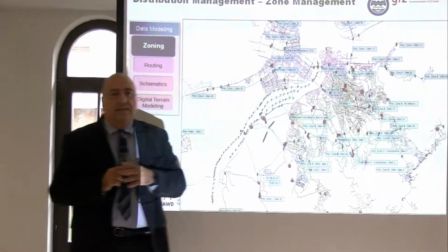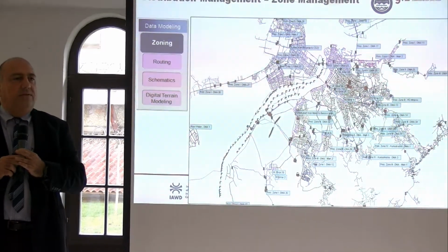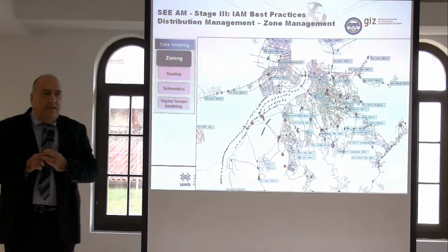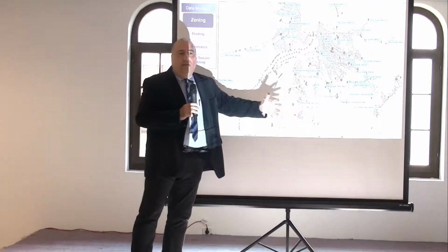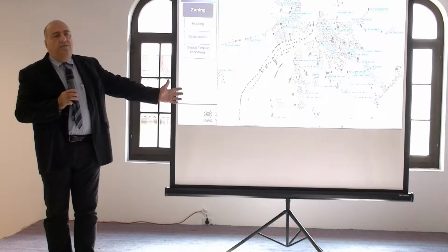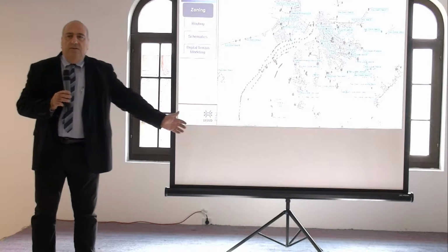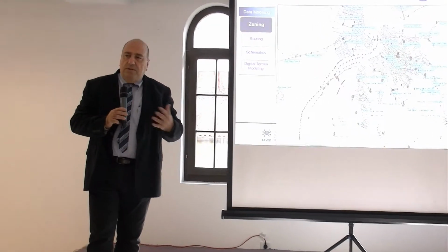They have something like 60, 70 closed zone valves. If one of them opens, it will be havoc, what's going to happen. Which strictly has to be closed at all times, and the energy cost is astronomical. I mean, you only have to look at the zoning, superimpose it on elevation, and get a feeling what's going wrong. That's why zoning is so powerful. It helps you understand how the system works. By just looking at it, if you understand a bit of hydraulic logic, everything makes sense.